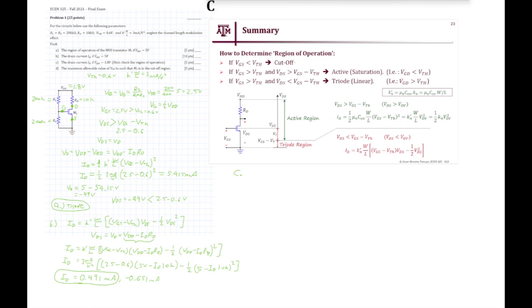Because our VDD is 1.8 volts, we need to recalculate our VG value. Fortunately, we can use the same logic as before: if these two resistances, R1 and R2, are equal, that means we drop half the voltage at this midpoint right here. Let me write this real quick. VDD is equal to 2 VG.